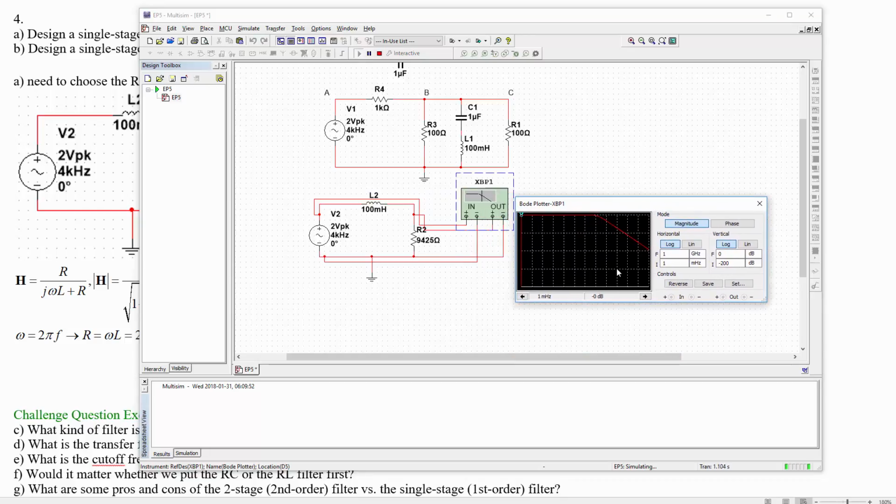So indeed, we've got our low pass filter and the minus 3 dB frequency. We need to zoom in around this 15 kilohertz, so that's a good sign. We're going to go up to megahertz and maybe up from kilohertz, and minus 3 dB, because the pass band is 0, 100% pass, so minus 3 dB would be around 15 kilohertz. So there we go. Made it work.